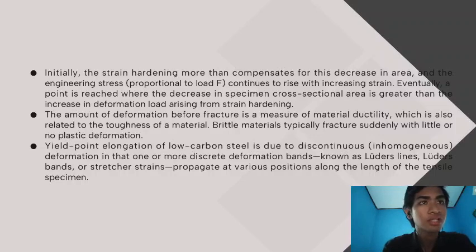For this material, the offset method cannot be used, and the usual practice is to define the yield strength as the stress required to produce some total strain, for example, epsilon equals 0.005. At other times, the slope of the stress-strain curve is described by plotting the secant modulus or the tangent modulus.